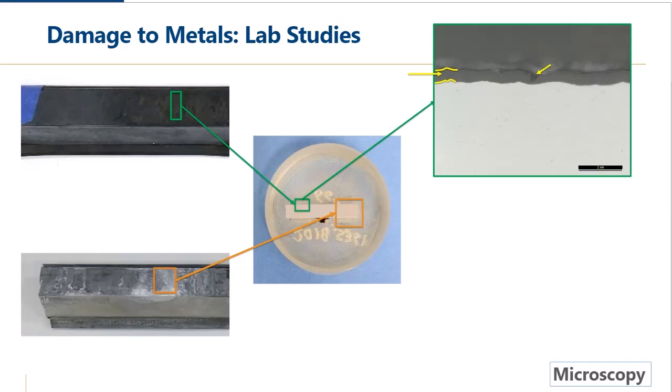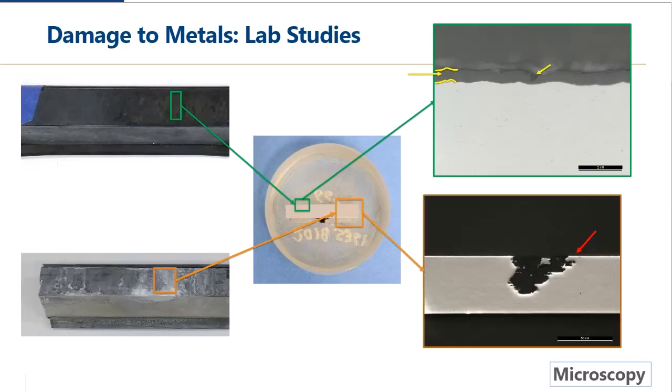But what you see, and that red arrow is pointing to, is this giant pit where about 2/3 of the thickness of the aluminum has been eaten away by chemical exposure in this area. And it's pretty localized, right? It's not a huge area, but you've got these pits in this aluminum where your aluminum is locally almost eaten away. And that is going to severely affect the performance of these aluminum windows as they're more likely to degrade once the degradation has happened.